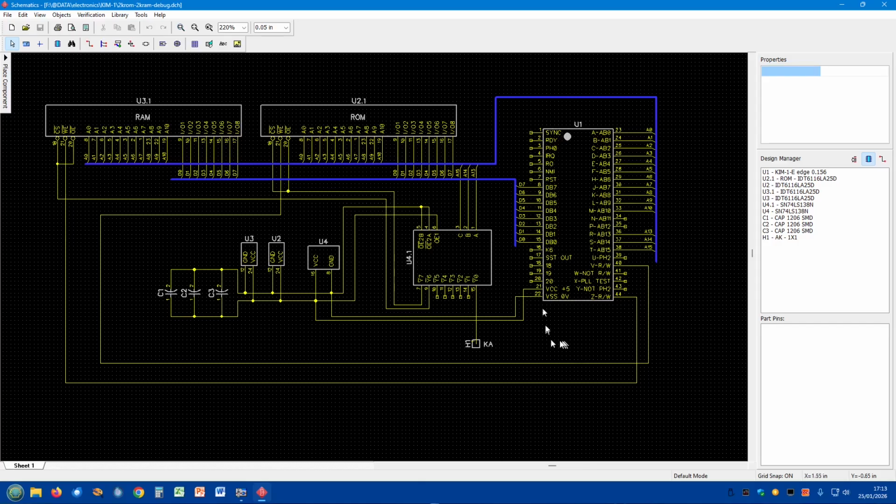Now the idea of this board is the ROM will sit right at the very top and the RAM just below it. So this is 2K ROM, but it will actually be sitting in the top 8K and it will repeat 4 times. I can put the reset vector in here and it will pick it up as being right at the very top at FFFC and FFFD, but when it runs the code it'll be running at a lower address. It doesn't matter. I've only got 11 addresses coming in there. You notice there's no address 11 and 12 decoded here. That's why this repeats 4 times.